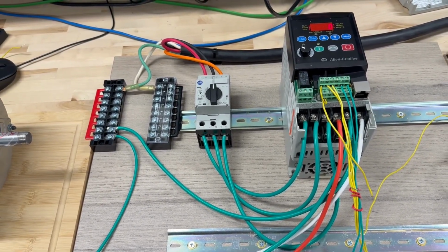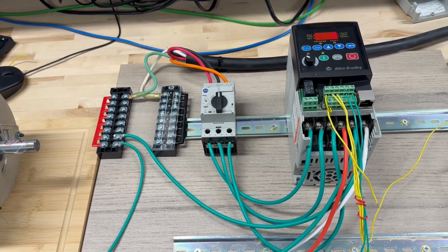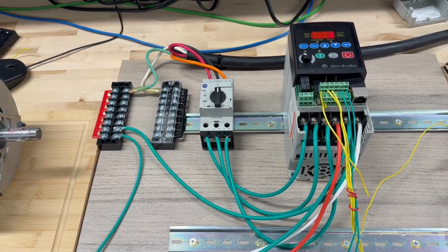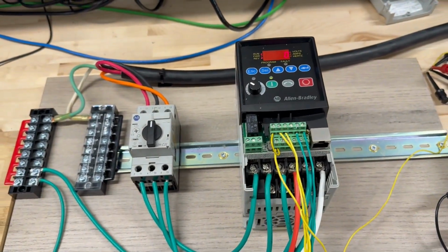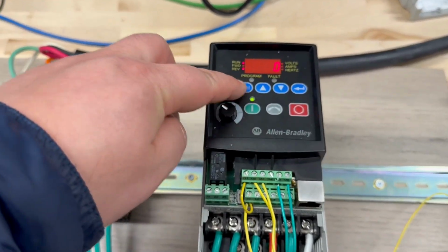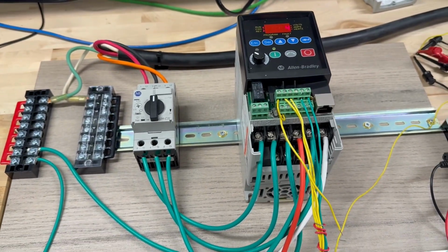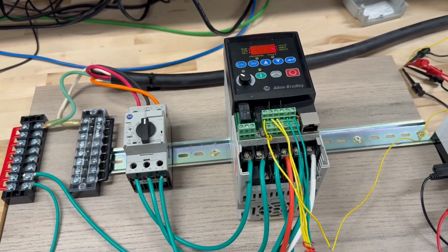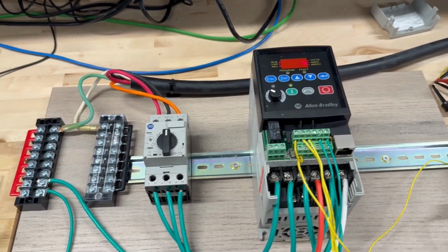P36 is all set. The next, P38, is an important one. Before, whenever we had the variable resistor, we put P38 on 2, which is 0 to 10 input, so we were able to have this remote variable resistor. Here we should set that to preset frequency. Let's check it. I go to P38. If you check the data sheet, it should be 4 for preset frequency with digital inputs. That number 4 is what I already put on P38.